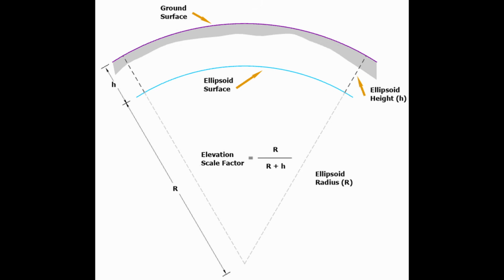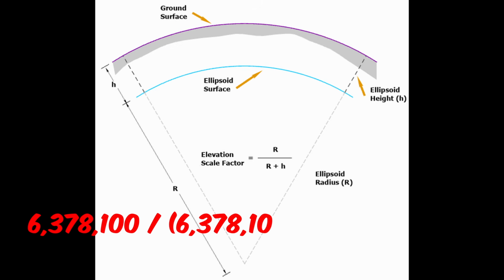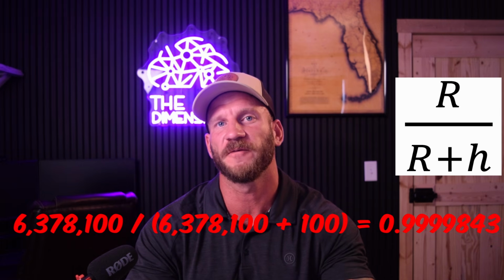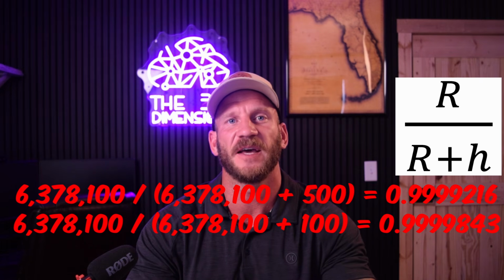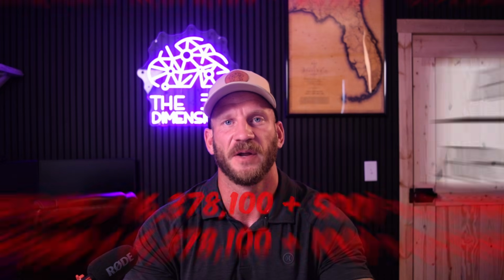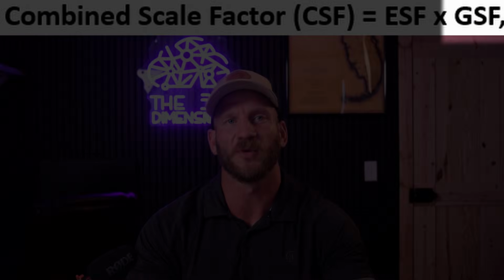You can see when the point we're trying to calculate the elevation scale factor for is on the ellipsoid, a value of 1 is returned and no distortion is added from the elevation scale factor. But as the point gets further and further above the ellipsoid, the scale factor gets smaller and smaller, which in turn increases distortion. Keep in mind that doesn't mean just because the point has an ellipsoidal height of 0, there is no distortion being added. We still need to apply the grid scale factor, which we will explore momentarily.